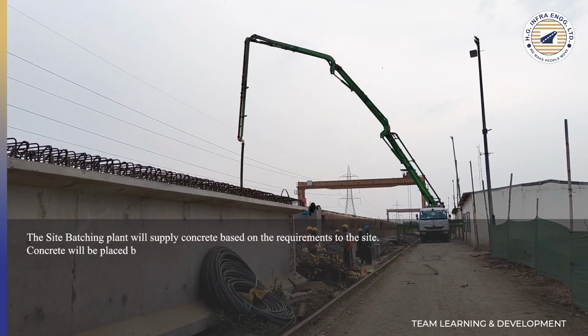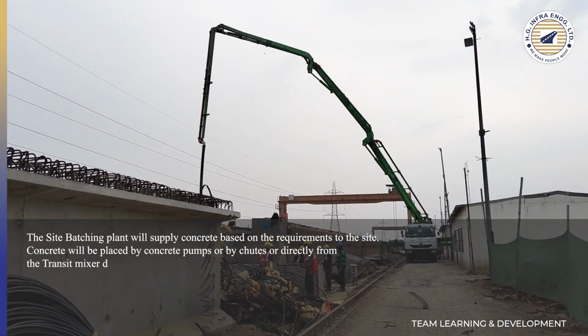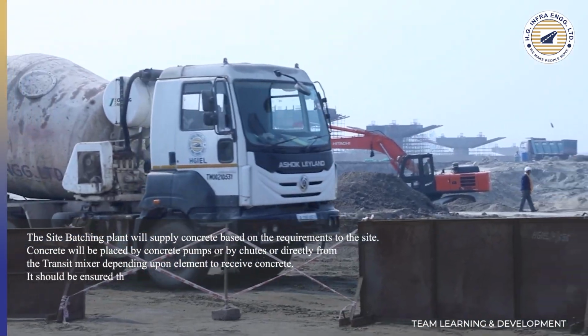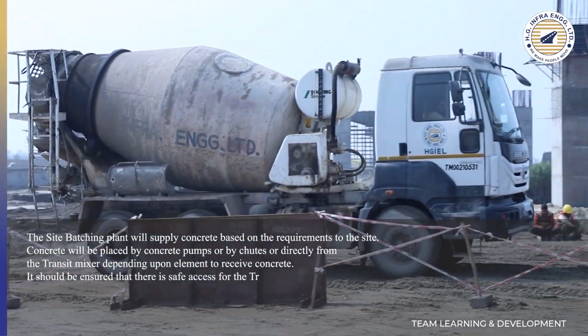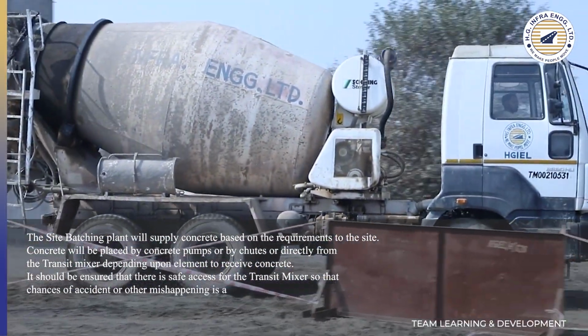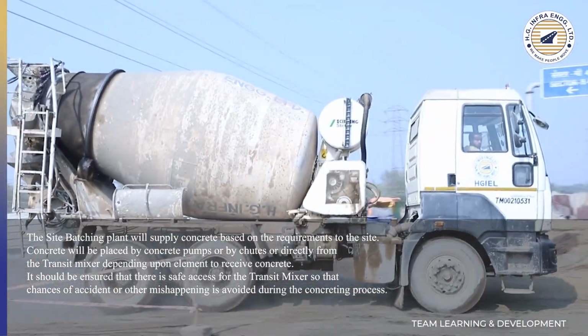Concrete will be placed by concrete pumps or by the chutes or directly from the transit mixer depending upon elements to receive concrete. It should be ensured that there is safe access for the transit mixer so that chances of accident or other mishap is avoided during the concreting process.